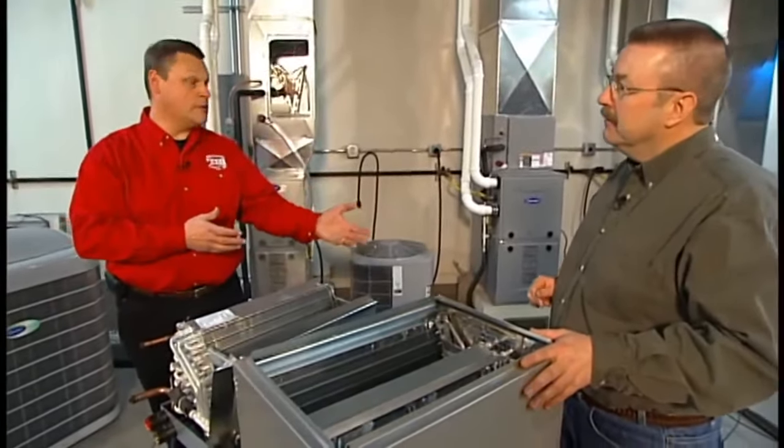So in the summertime, it's even more important that as we're running the continuous fan to do a couple things. One, there's a lot more pollen in the air. So by running the fan, it allows us to clean the air. Secondly, it helps balance the temperature in our home. So that hot air that rises, if we didn't run the furnace fan, it would stay up there until we finally had a call for cooling. What we would rather do is have that airflow continuously move around through the house. It may actually save you from having to run your air conditioning as often because it can take that cold air that migrates or collects in the basement, reutilize it and distribute it back throughout the remainder of the house. So it's a win-win that way. Clean air as well as less operation of your condensing unit.